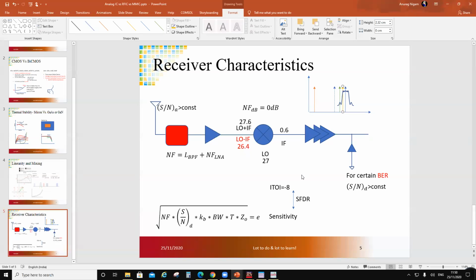But look at the yellow one. Yellow is halfway between the two. So what's the frequency of this one? This is going to be LO plus half times IF. Correct? Now, is this component suppressed? Answer is no, because the sharpness of this fall off of the BPF was not enough. So this is the component which is suppressed very little. Now how is it going to hurt me?